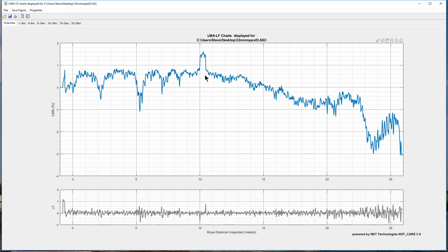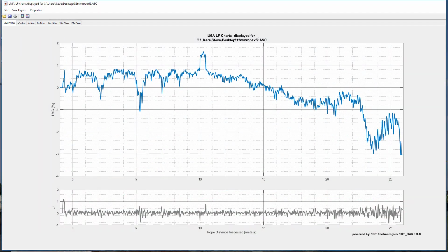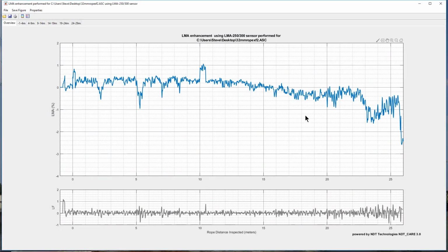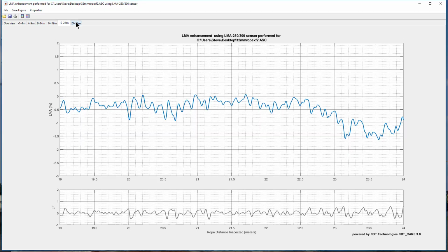This is referred to as a moving calibration inspection. Notice just to the left or right of the calibration wires the area where the echo effect has been eliminated. Again, I will scroll back and forth: the original signal and the enhanced signal. I can then go back and change the axis scaling if I choose. And maybe for this plot I only want to go down to -3. All of the various zoomed tabs will take on that setting as well.